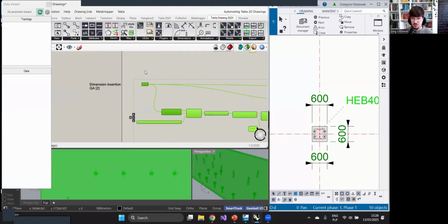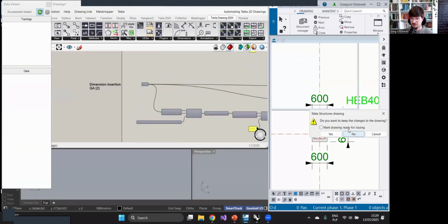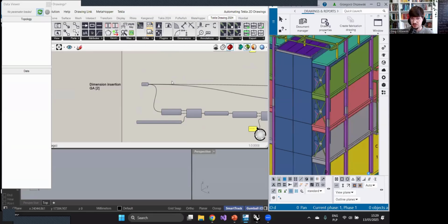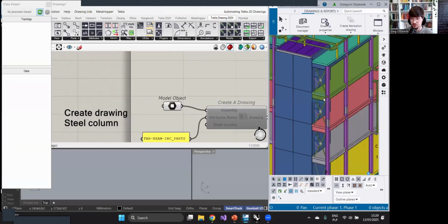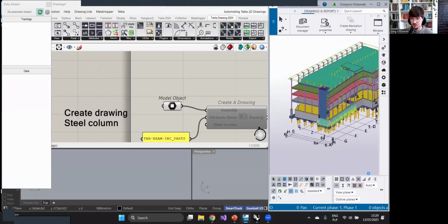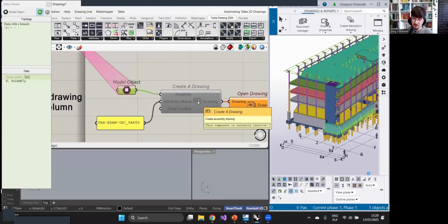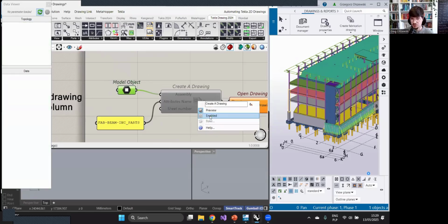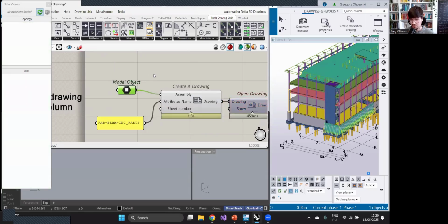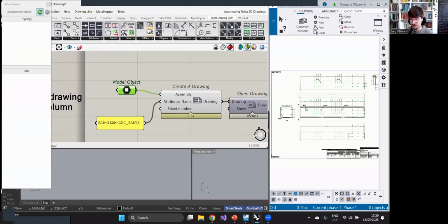But of course, for someone, it could be quite tedious to do all of that. And for them, there is just a lazy way, where you can create the drawing just like you would do as a user. So you can just query this create assembly drawing, cast unit drawing, or GA drawing, and that will just create the drawing, and later it will open it. So now I have just asked Tekla to create the drawing. And of course, you can do exactly the same as the user with the right click, create fabrication drawing, which is the common path.